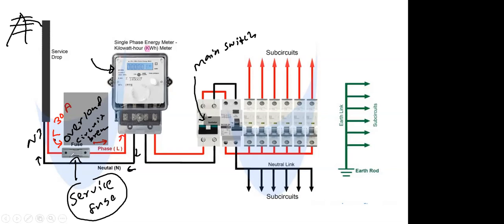So I'll label now the most important ones before you get the electricity supply. Number 1, overload circuit breaker. Number 2, electric meter. Number 3, main switch or the isolator. What is the role of the main switch? Whenever necessary, when you are doing an electrical repair, or if someone gets electrocuted, or in case of an electric fire, you can switch it off manually. You can switch it on and off manually when necessary. The overload circuit breaker, if the load from the national grid goes beyond the limit, will disconnect the supply, protecting the devices in your house.